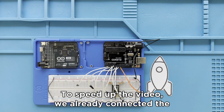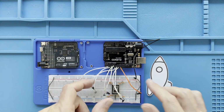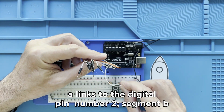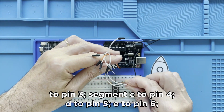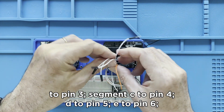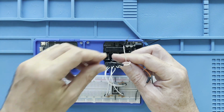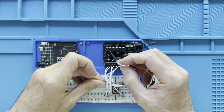To speed up the video, we already connected the resistors to the display pins. We can continue to connect the display to the Arduino. Segment A links to the digital pin number 2, segment B to pin 3, segment C to pin 4, D to pin 5, E to pin 6, F to pin 7, G to pin 8, and the decimal point to pin number 9.